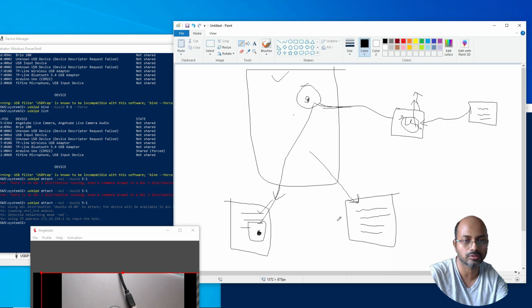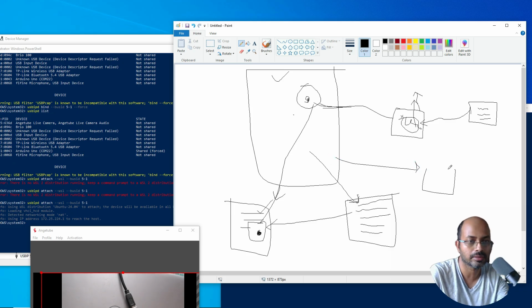You cannot assume. What I mean to say is, you are sending the command from here. You could have directly connected from here and got the XY instead of asking him, because you know this. But he may not be the only client. There may be many other clients asking for commands from him. While he is moving the robot, he might be asking get temperature. And if both are asking for move, then you don't know whom to subscribe, whom to directly sync with. So this kind of abstraction is very important and helpful, and that is what ROS2 is giving us.